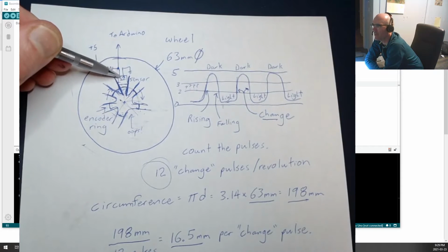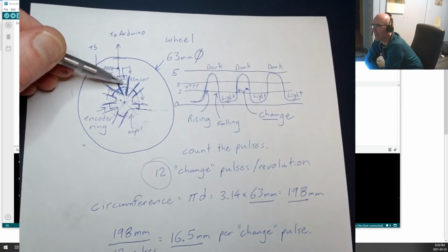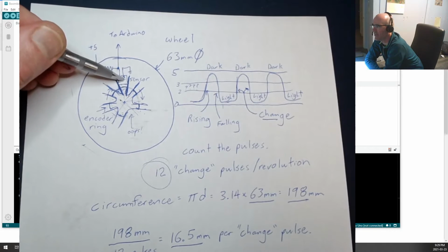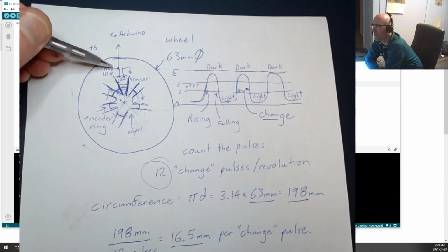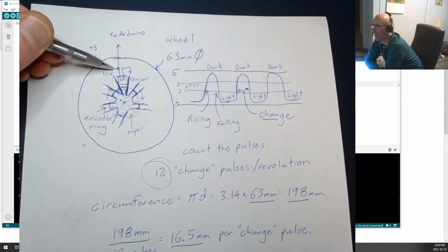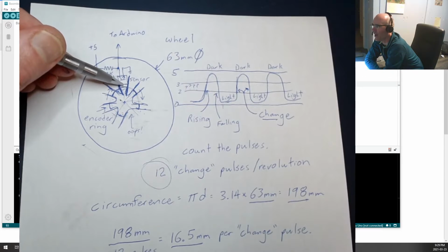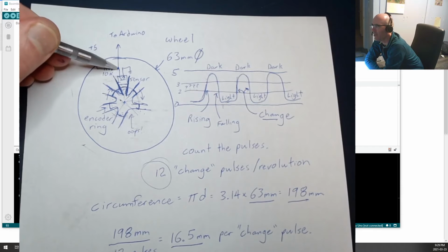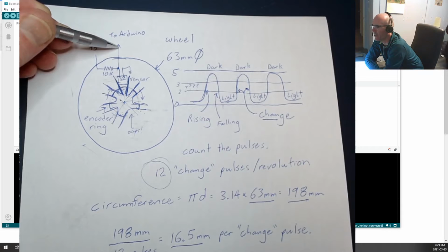It flows through the resistor right here. And if light's hitting this, then it flows through here very easily and comes to ground. And if there's no light hitting this, then it really doesn't flow at all. And whether light flows through here or not determines whether there's current flow, and that determines whether there's current flow across the resistor and whether there's a voltage drop across the resistor or not. So when we've got white right here, the white hits here, current flows to ground, pulling this pin low. And this, we've got tied into an Arduino pin.